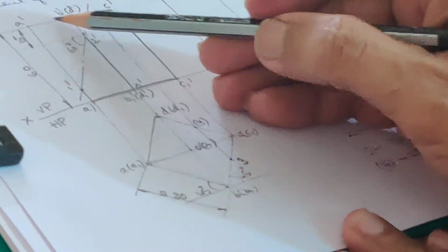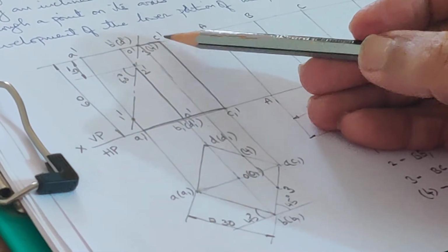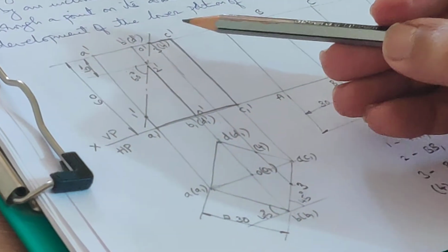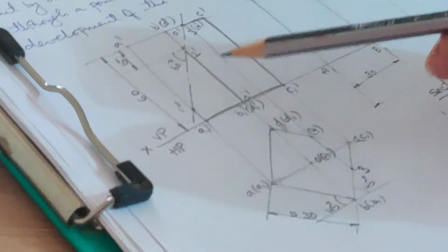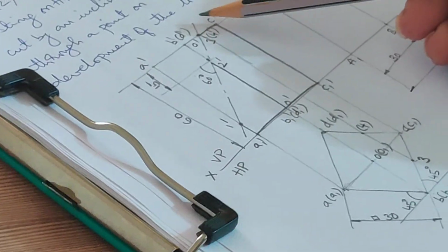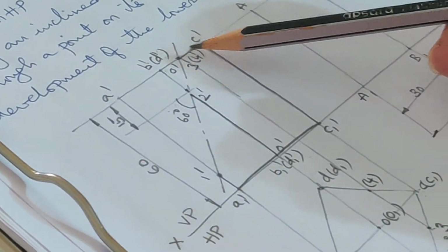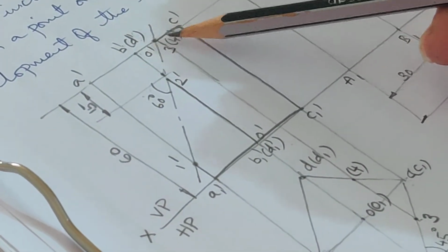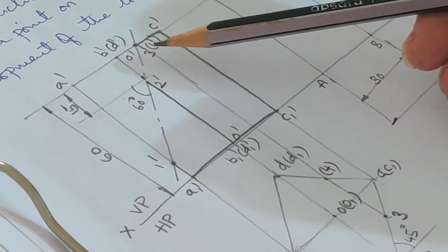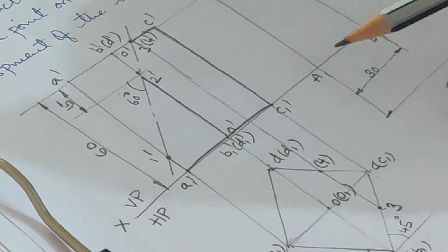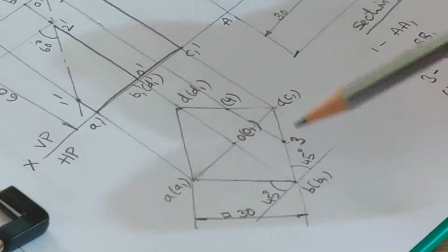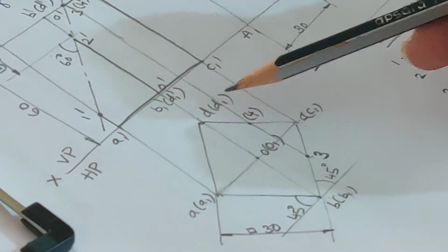So whenever it cuts a base, make it a point that two section points have to be named. I repeat once again, whenever the cutting plane cuts a base, the section point has to be named as 2 points. 2 points correspond to two different base edges. So here 3 is on BC, 4 is on CD.